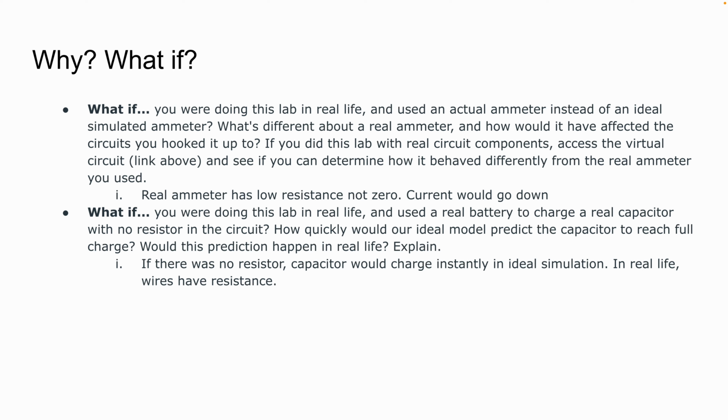What if you're doing this lab in real life and use an actual ammeter? Well, a real ammeter has low resistance, not zero, so we could expect that the current would go down. And what if we used a capacitor with no resistor in the circuit? In the simulation, the capacitor would charge instantly. In real life, the wires have resistance, so it would probably take a little bit longer.